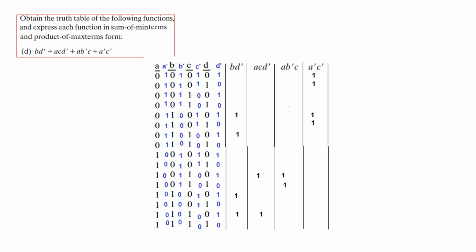And then we have A and B dash, C, no, none. Okay, so A, B dash, C, only 2 terms. And finally, A dash, C dash. So let's see from here, A dash is 1 here, so we'll pick from here. Now C dash is 1, so 1 and this 1, and then again C dash is 1 here, so these 2 terms, and rest not possible because A dash is 0.